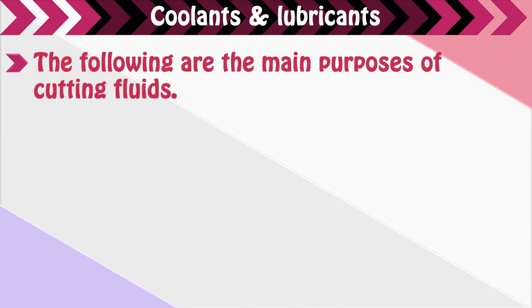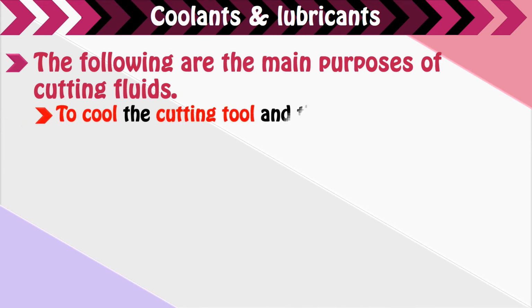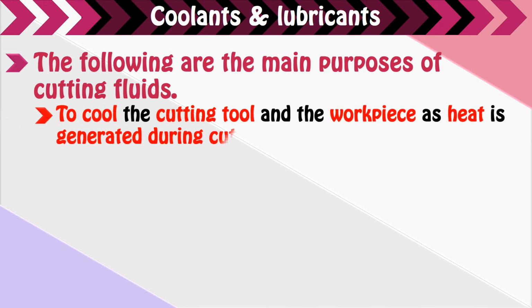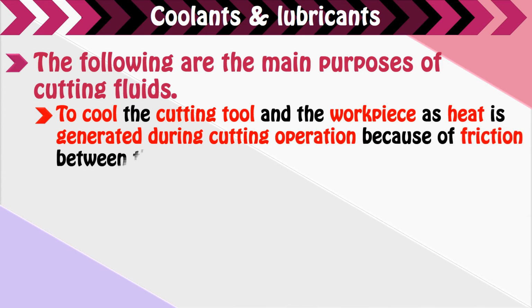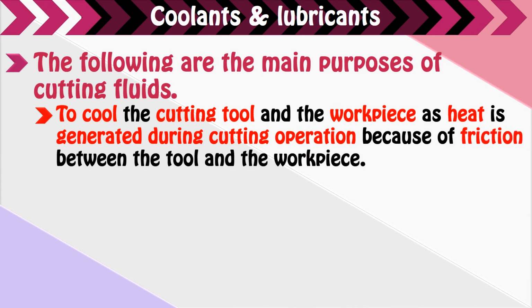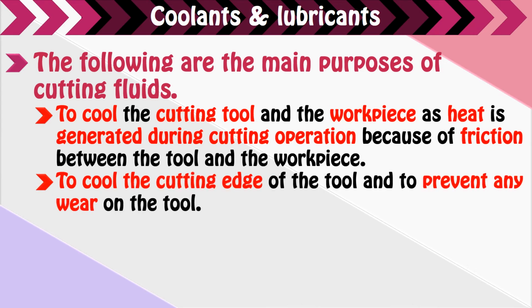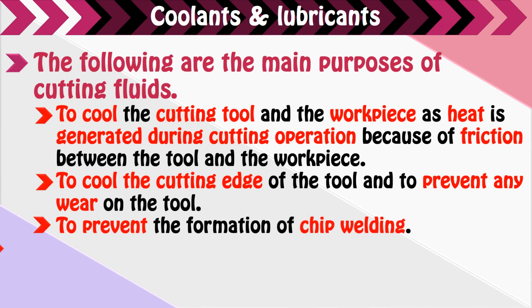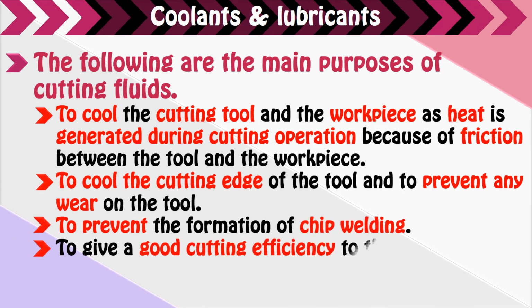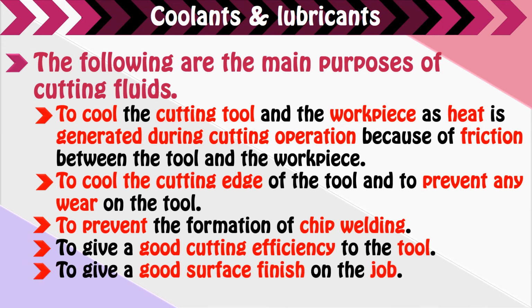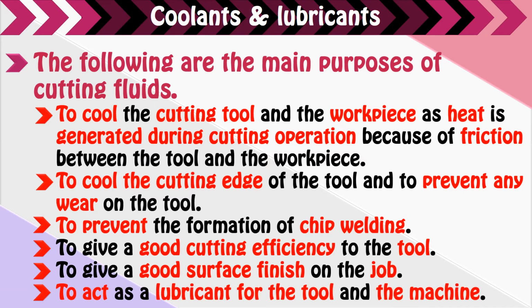The following are the main purposes of cutting fluids: to cool the cutting tool and the workpiece, as heat is generated during cutting operation because of friction between the tool and the workpiece. To cool the cutting edge of the tool and to prevent any wear on the tool. To prevent the formation of chip welding. To give a good cutting efficiency to the tool. To give a good surface finish on the job. To act as a lubricant for the tool and the machine.